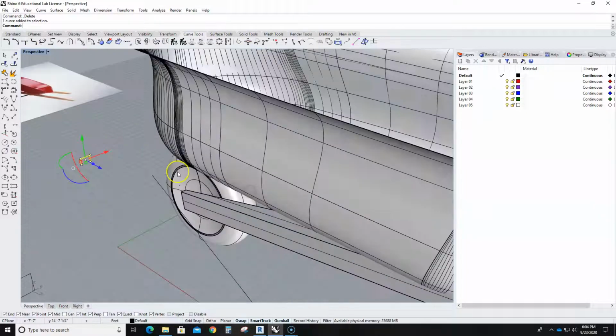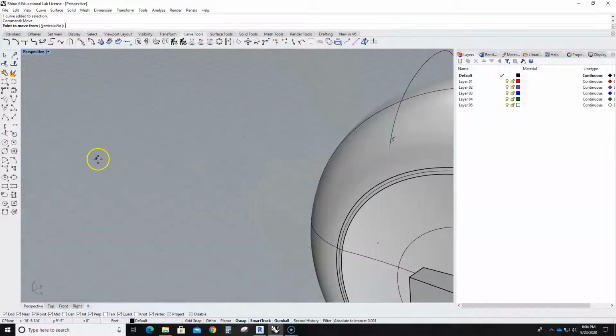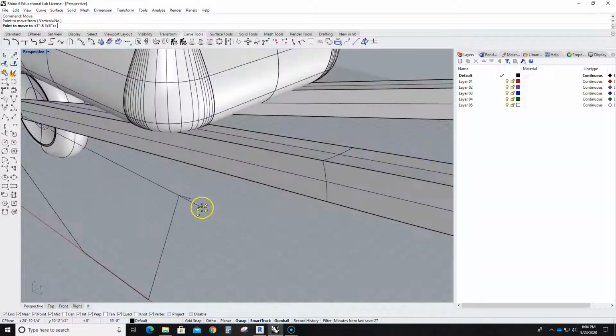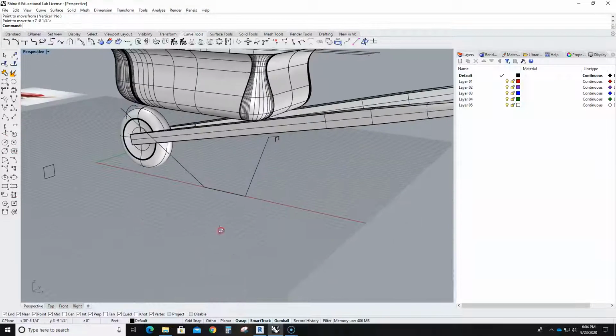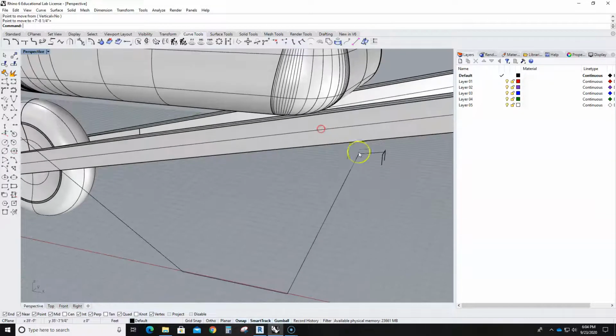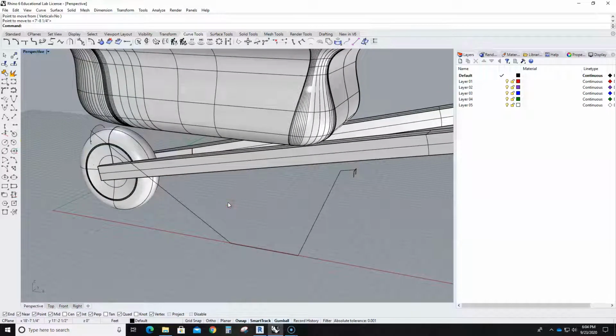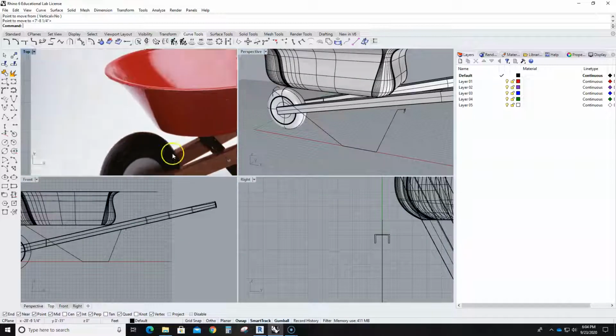Now I kind of want to move this to this using the center midpoint. I'll grab that midpoint and put it right at that end section. Actually, I'm not quite sure how it's going to sweep, so we'll see. Actually, I need to fillet a couple of things.